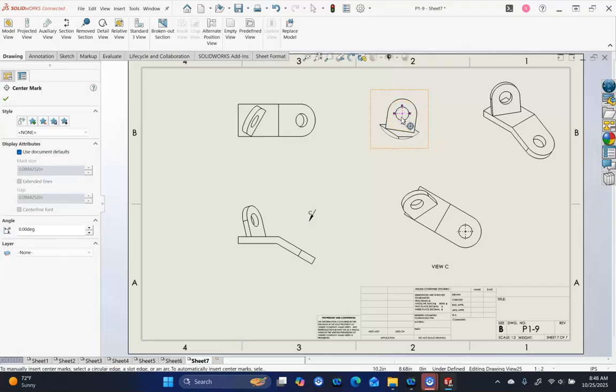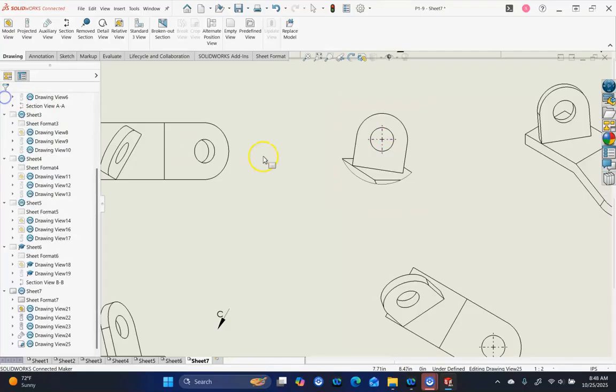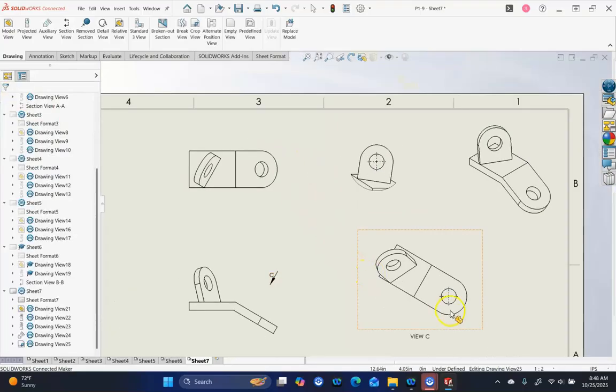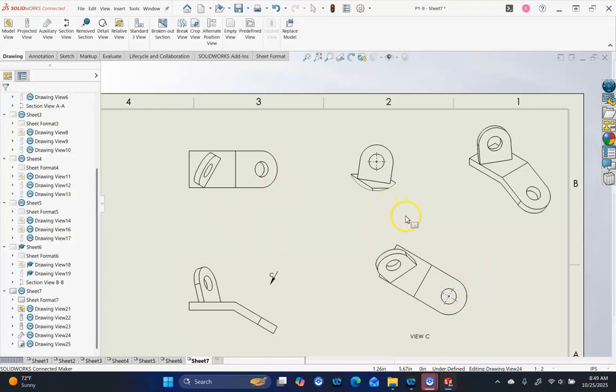So let's see the center line then. I'll go ahead and correct. We want to verify the alignment. And actually that one doesn't look like it's picking up. Okay, so we'll have to revisit that one, figure out what that angle is then. You know, on the auxiliary views, what I'm looking for is, so that one went to -60 degrees. If we go 0, then it aligns to the view that we're looking in, and when I place the dimensions, they won't try to skew.